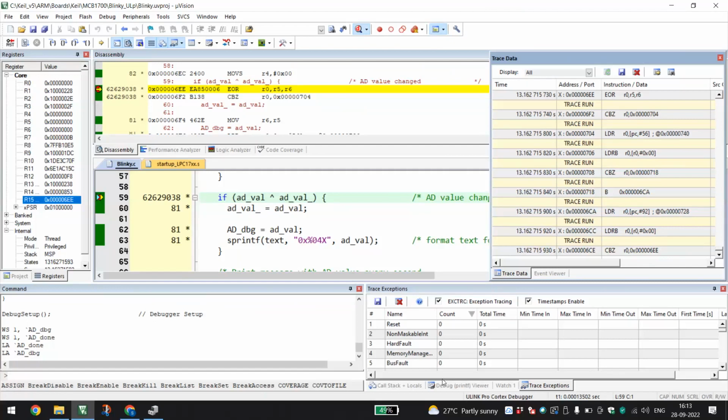Coming to the debug printf viewer, it is for viewing debugging and program specific information. The performance analyzer view is used to view the execution statistics and the instruction trace for a particular instruction with the time, and we have an event counters window that displays the counter for each user selected event.